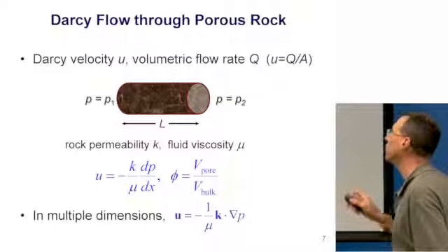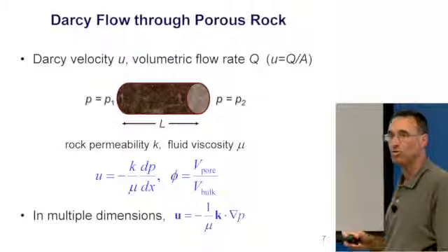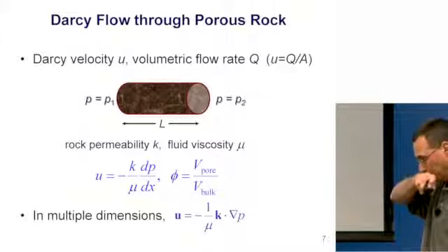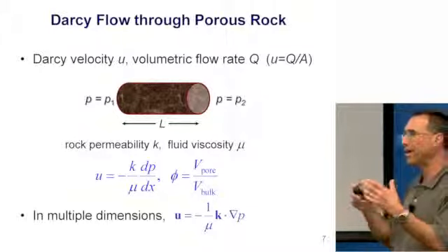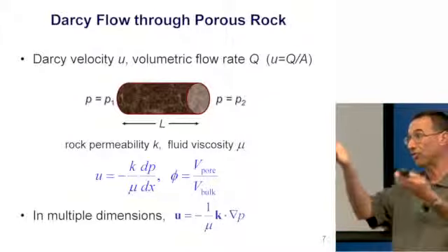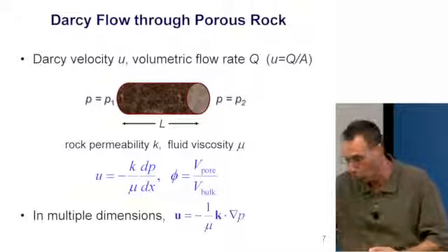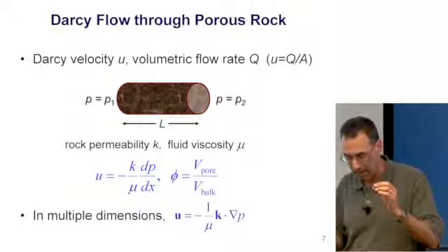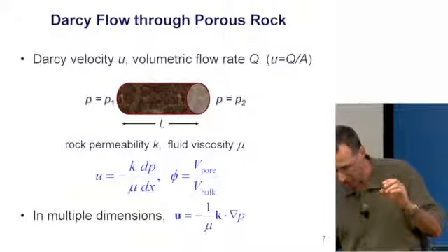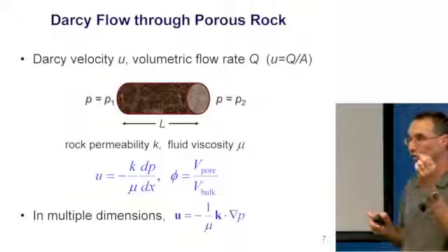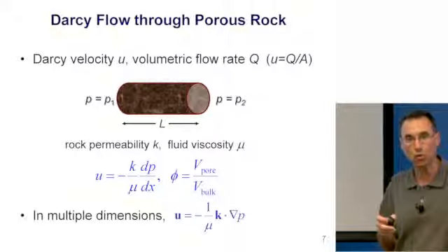So let's talk a little bit about how flow in the subsurface works, and then we'll get back to the CO2 storage problem. A lot of people have this image that you drill down, say if you're producing oil, and there's this pool of oil. That's not how it actually exists. The oil or any fluids in these formations essentially lives in the pore spaces between sand grains.